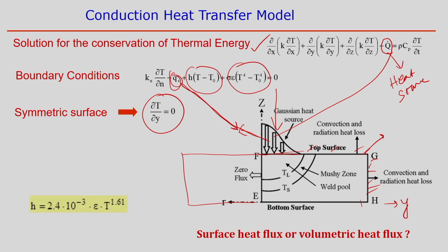And it is the K, the heat conduction: what is the value of heat conducted on the surface at this point, K is defined over the surface only. So, that makes a balance in the heat transfer. So, this can act as a boundary condition, and solving this equation over the whole domain, we will get the temperature distribution. It is a 3-dimensional form, but in the finite element model, suppose this is the node,